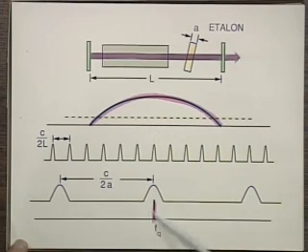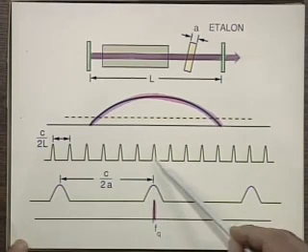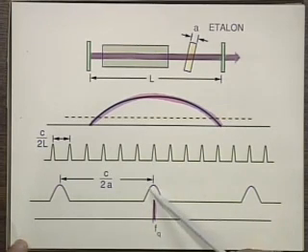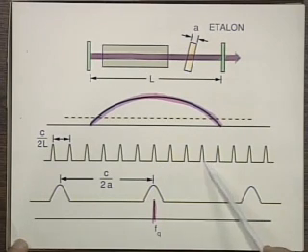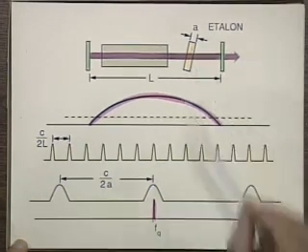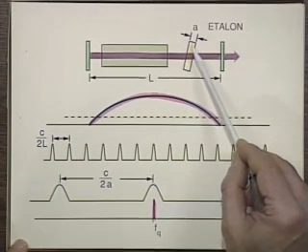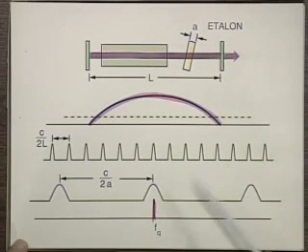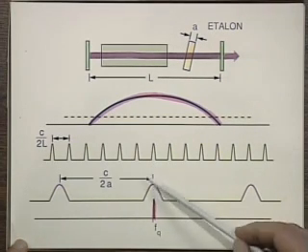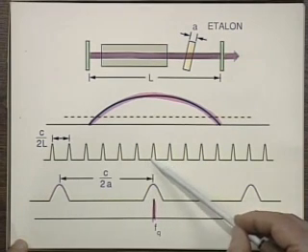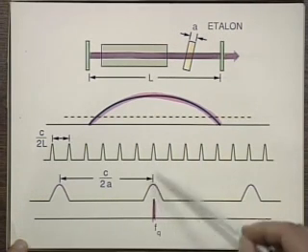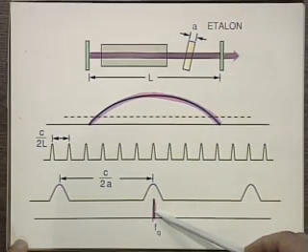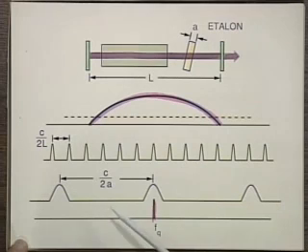In the cavity, the laser will oscillate at this frequency, which is determined by the overlap, the product of these two. At any other frequency, while before they oscillated, now they see this loss, because you're off resonance with respect to that cavity, so the transmission is low, and they will not oscillate. Only at the overlap between the short cavity and the long cavity will you get enough gain to overcome the loss, and then you'll get lasing. At any other value, you don't. So this is a way of selecting a single frequency.